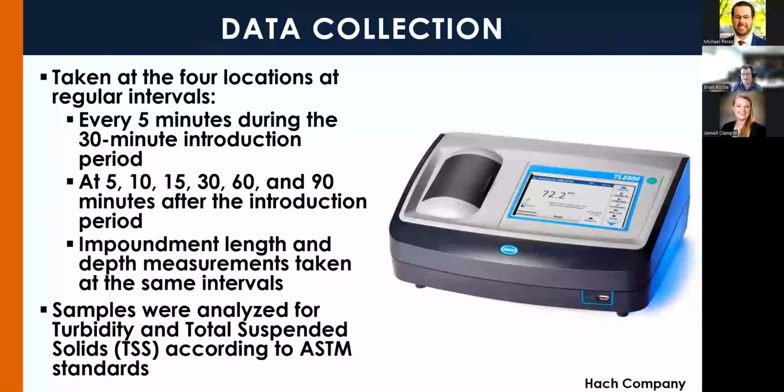We had 5, 10, 15, 30, 60, and 90 minutes after that introduction period to see how the system is dewatering. At the same intervals, we also took impoundment length and depth measurements as well. So we took these samples back to our lab and we analyzed them for turbidity and total suspended solids according to ASTM standards.